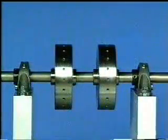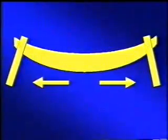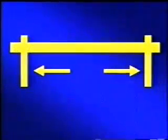A rotor which is bowed between the bearings actually has an unbalanced condition, but exerts axial force on the bearings. The bend causes one side of the rotor to be longer than the other, forcing the bearings out during part of the rotation and letting them flex in for part of the rotation. This makes it appear as if the ends of the shaft are moving in opposite directions, while for a straight shaft, the ends are moving together.